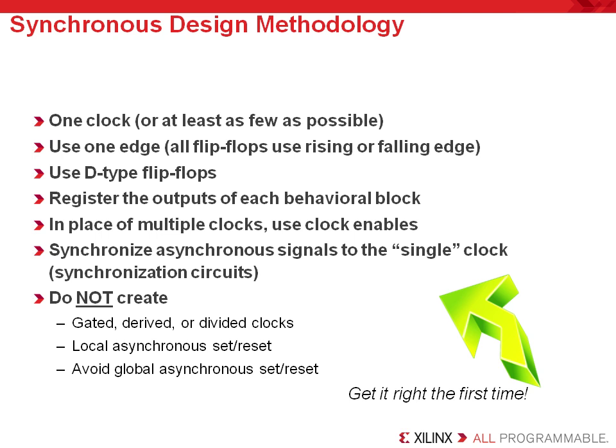Now, D-type flip-flops are not so much a requirement as a suggestion. When you use the D-type flops, this reduces the combinatorial logic on your data paths since the D flip-flops were already built into the FPGA. Registering the inputs and outputs of each block enables effective timing estimation when pipelining. Likewise, this is the easiest form of pipelining a design.